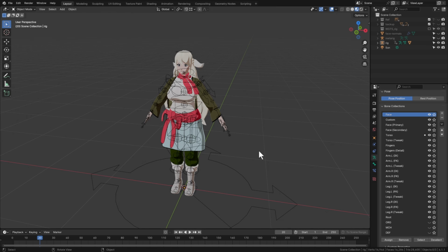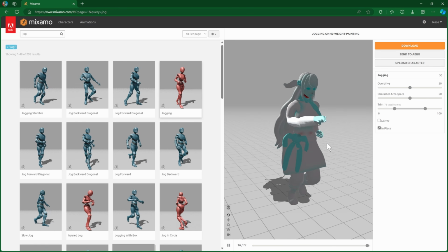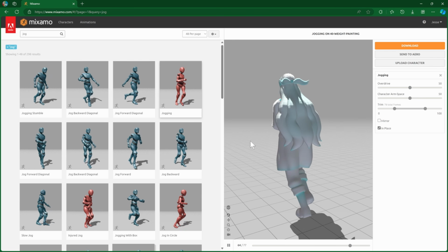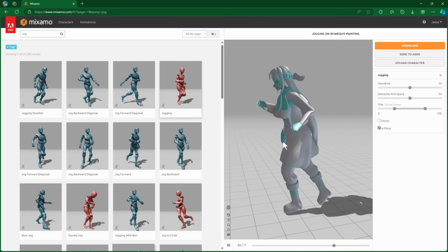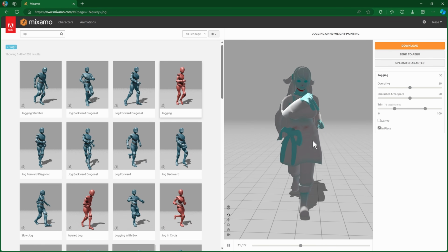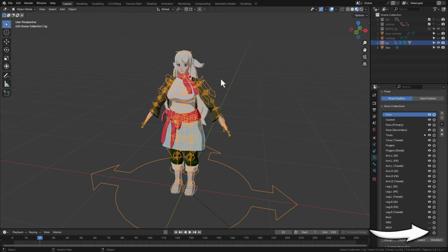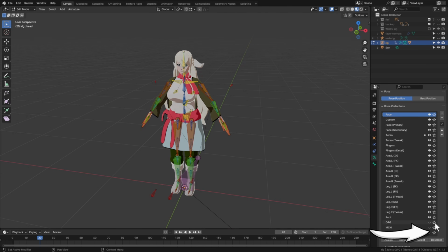Before we can use Mixamo, we will need to make the rig compatible with Mixamo. I'm recording this in post, but if we export the armature as is for Mixamo, Mixamo will give strange results for the arms and legs in the animations. That's because the Rigify armature has 2 bones for each part of the arm as opposed to 1. To fix this, enter Edit mode on your armature. Click the star icon next to the def bone group to see only the deformed bones.